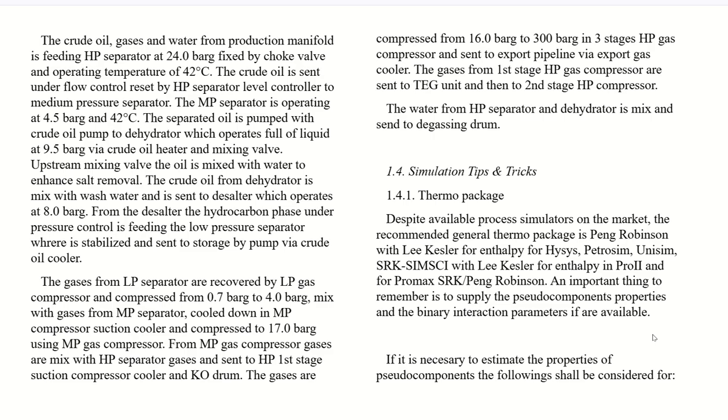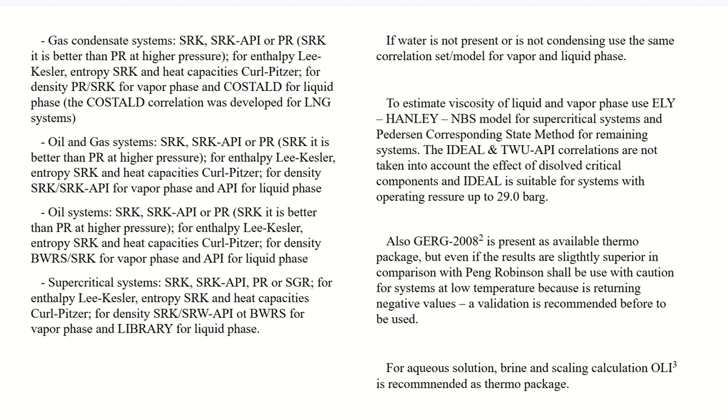Pseudo components are not crude-defined true components; they can be the higher components, and you can simulate them in HYSYS, where there is a pseudo components option. It gives some information about the pseudo component, like for a gas condensate system, SRK API is better than PR at higher pressure. For enthalpy, Lee Kesler; for entropy and heat capacity, SRK.